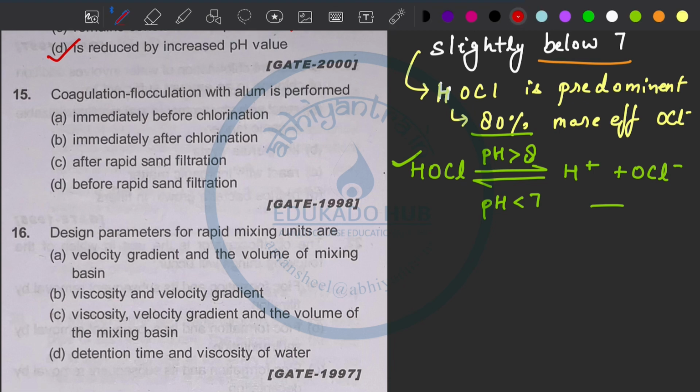And the removal of chemical solids is easier than removing turbidity solids from surface water, and therefore higher filtration rates can be used, and this allows the use of smaller filters which reduce the treatment plant size and capital cost.